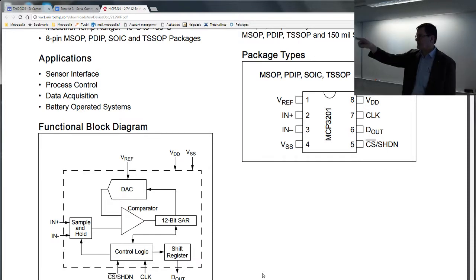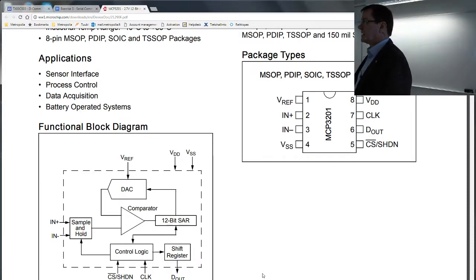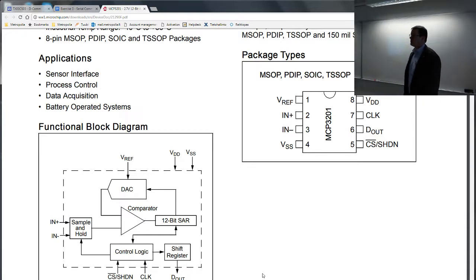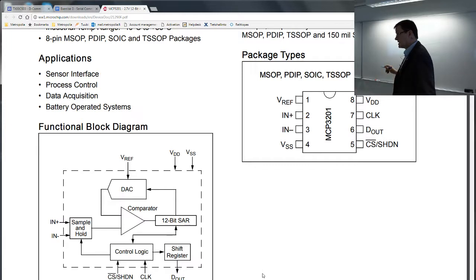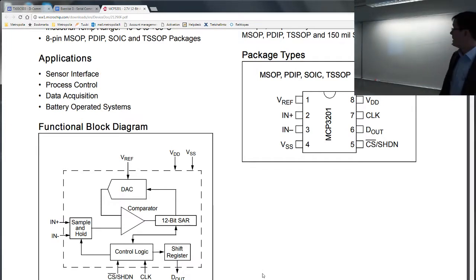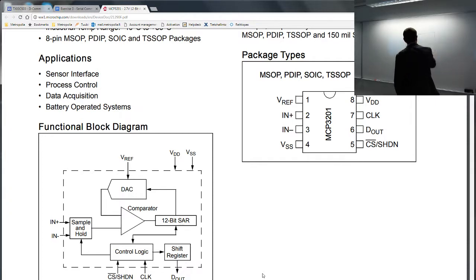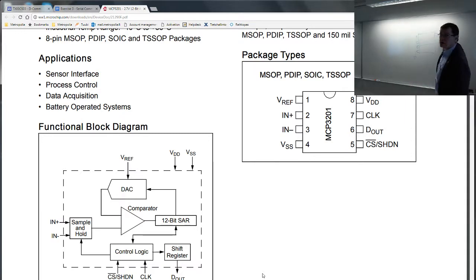The other thing is they're also pretty cheap, so this is a very cheap A to D converter for plenty of different purposes. A couple of notes, which I have also given you as hints on how to connect this one. So, reference. VSS is the ground connection. Then on the top corner there's a VDD, which is the power supply. In our case that goes to 5 volts.